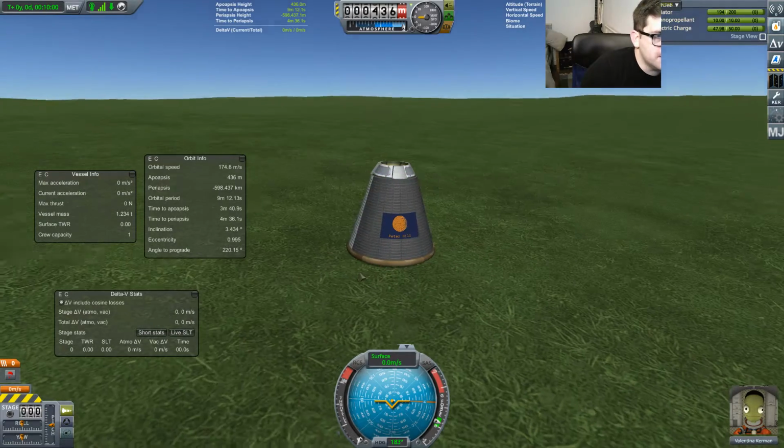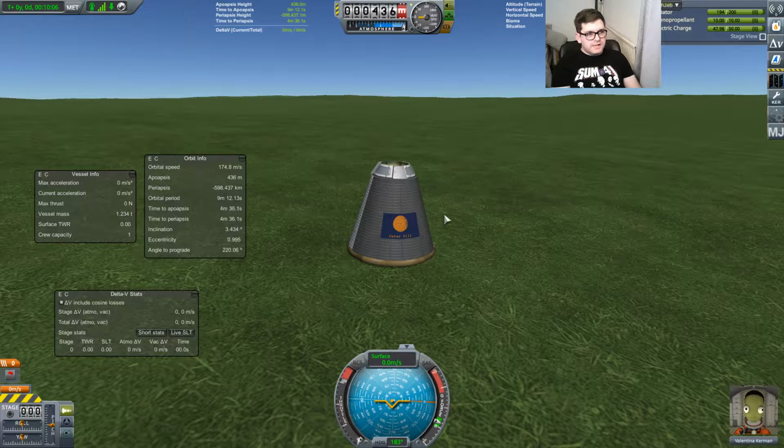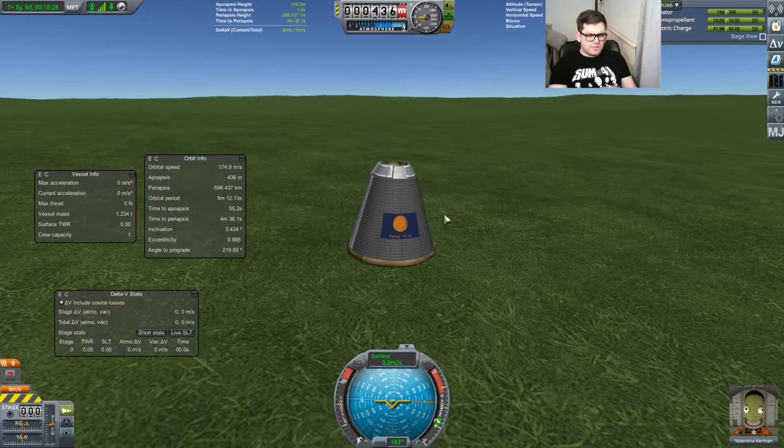And that is it. Okay, so we have gone through delta V, ISP or specific impulse, thrust to weight ratio, getting into orbit. Okay, so orbit, I didn't explain this earlier, but basically orbit is you're perpetually falling sideways. So the best way to get into orbit is to accelerate sideways, because as you're going along, the gravity is pulling you down.